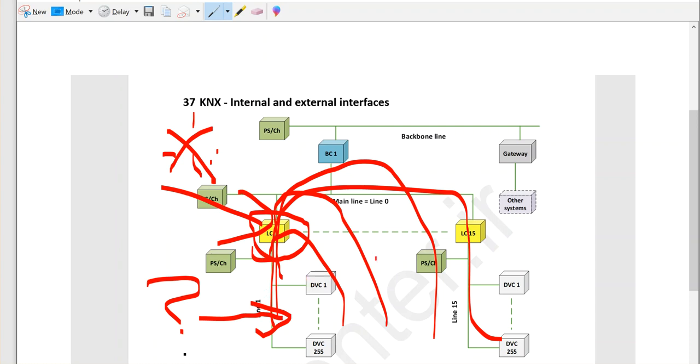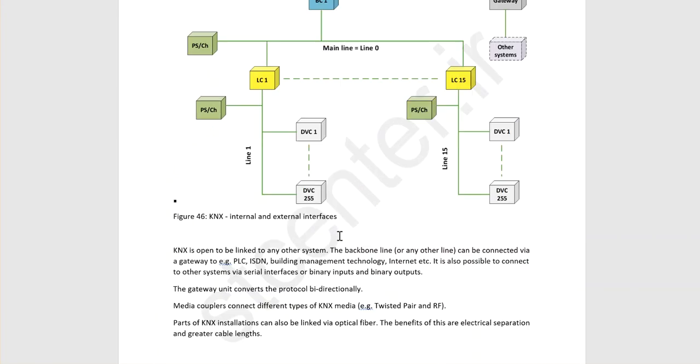But if you have, for example, a building with 1,000 or 500 Hitachi split units, and all of them have only one gateway to BACnet, and you want to use BACnet to KNX, you put the BACnet to KNX gateway on the backbone line or main line and communicate with all the devices through that one. Yeah, it's interesting. I hope it would help you.